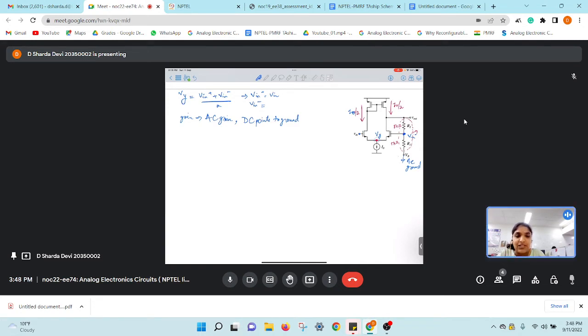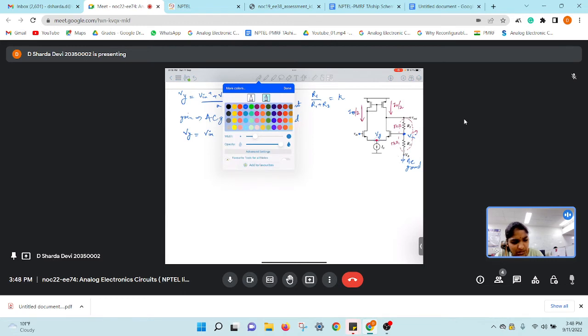So Vn minus will be there only due to Vout. Now what will our Vn minus be? R1 upon R1 plus R2 times Vout. So this is our Vin plus and Vin minus. So we'll get our Vy to be, let's say R1 by R1 plus R2, we name it K for our simplicity, okay?